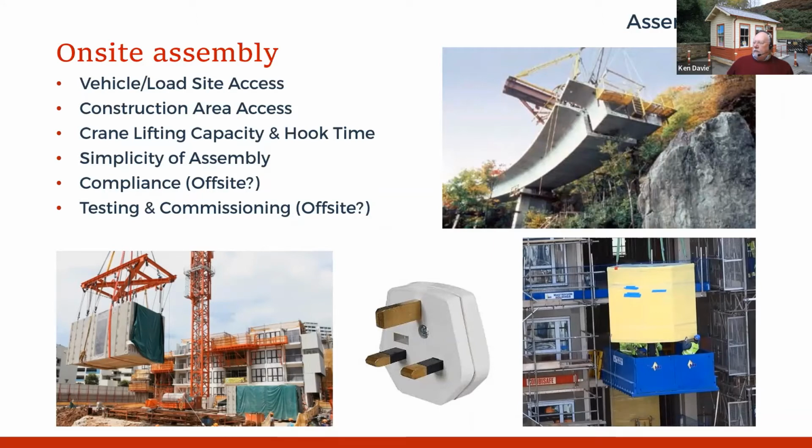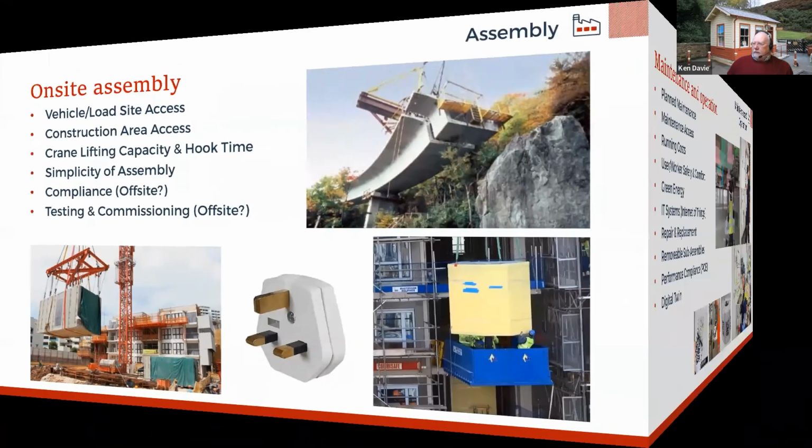If it's a repeated element, something being manufactured which is going to be used multiple times, you can have a prototype made, set the standard for that, and have that as your quality check. Almost like you're doing your snagging in the factory before anything arrives on site. Possibly an awful lot safer, an awful lot simpler. So that's the assembly stage.